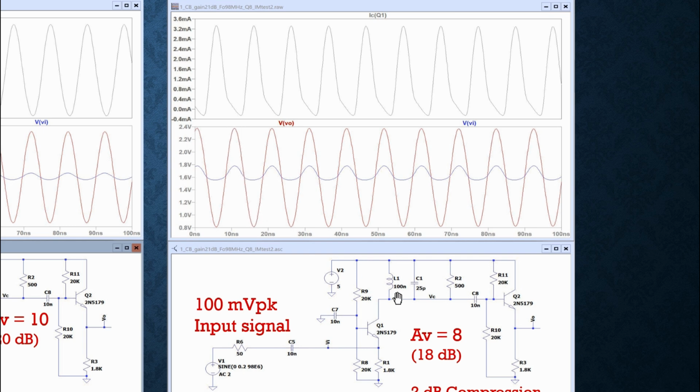Why is that? Well, we've got an LC tuned circuit here. So it will take this waveform and filter out all but the fundamental and leave a beautiful sine wave. But here's what's really happening. This collector current waveform looks pretty bad. And the reason is this input voltage is varying the base to emitter voltage. The base is held constant with this bypass capacitor, but the input signal is coming in on the emitter. So the base emitter voltage in this transistor is varying. Of course, that's what makes an amplifier work. That changes the collector current, but it's varying too much.